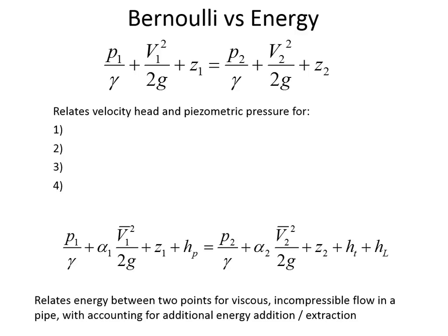Any questions about a pump? Pump head will have the same units as all the other terms have. Our pump head will have units of length. Isn't there where the pump is on the right? Good question. No. All it matters is that it's between 1 and 2 in the energy equation.